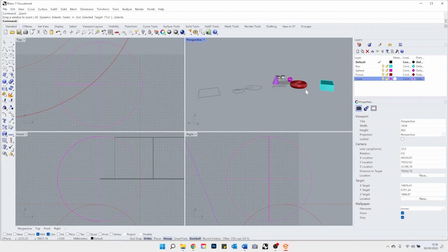You don't know where it's located on your canvas because you have this unlimited canvas in Rhino that you're going to be working on. You could be a couple of kilometers away from the 0 point. When you open your Twinmotion or any other rendering package and suddenly you import your model in and it's not appearing, it's like, what's happening? It's actually just because it's located so far away.